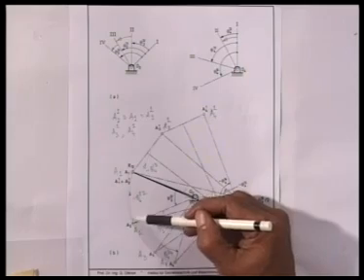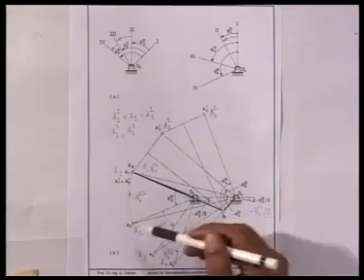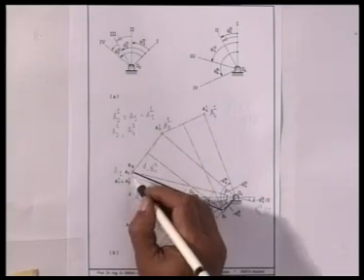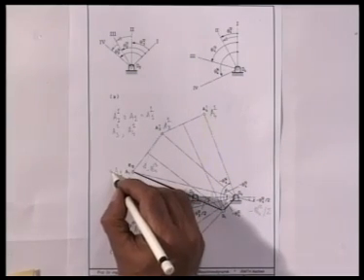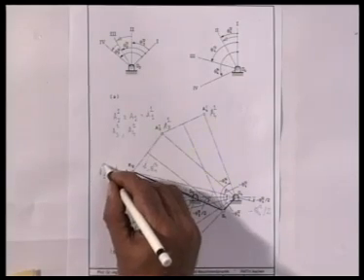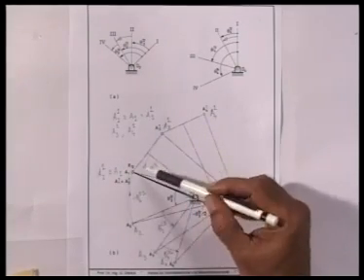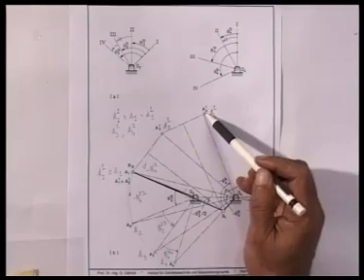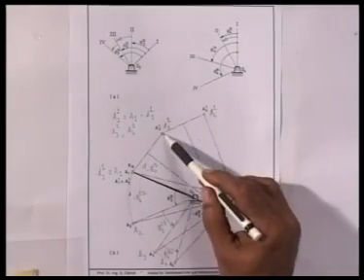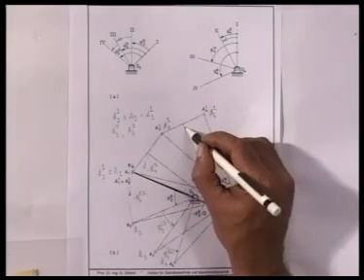By the inverted position of A2, when I rotated O4 A2 through minus theta 4 1 2, I got to the same point. So, A1 is the same as A21. Then the center of the circle passing through these 3 points is found from the perpendicular bisector of this line and the perpendicular bisector of this line.